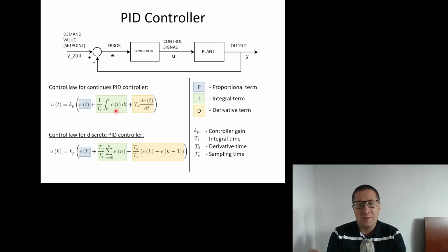It will then be the P controller, or PD controller if the Td value is higher than 0. And of course, in the distributed control system, we can open the control sheet, click on the controller algorithm, and we can check what are the weights related with each term and what is the nature of this controller.